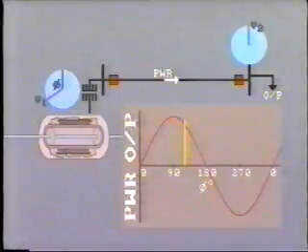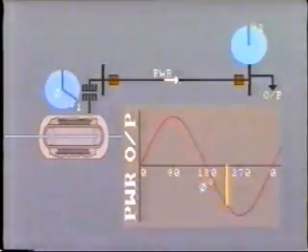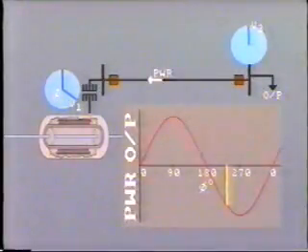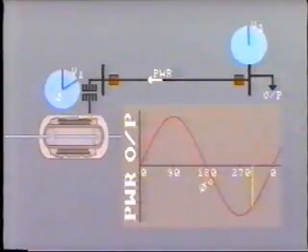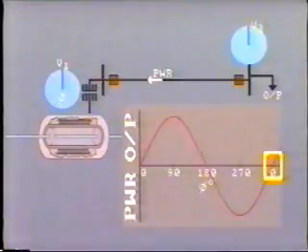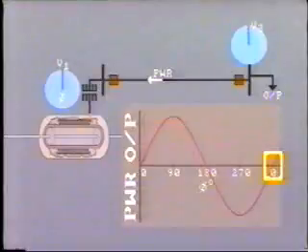As the rotor continues to advance beyond 90 degrees, the amount of power being transferred along the line decreases until, at this point, the rotor is leading by 180 degrees and there is zero power transfer. As the advance continues, power begins to flow in the other direction, that is, into the generator from the system. The generator rotor has advanced so far that it's now coming around again and is beginning to catch up with the system. It then reduces to zero as the angles coincide. At this instance, the voltages at each end of the line are in phase, and load transfer is zero.